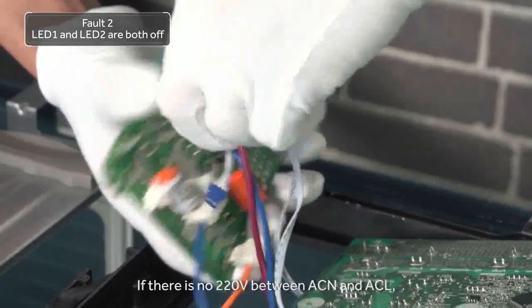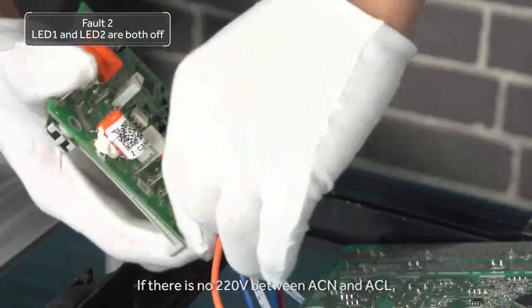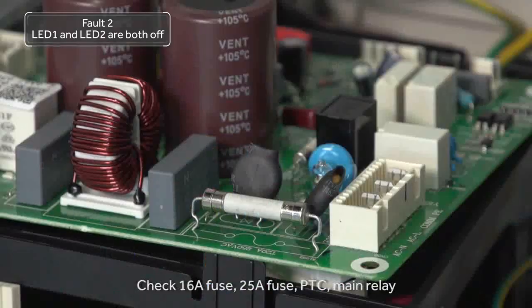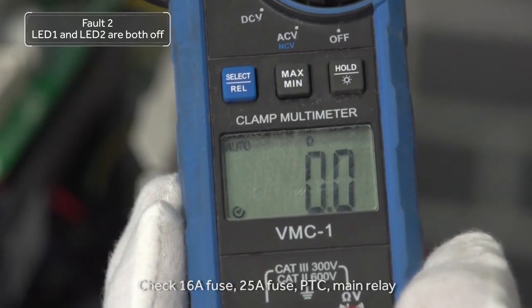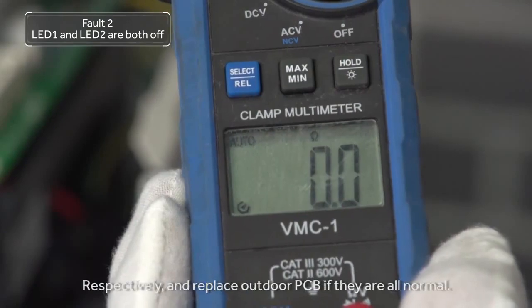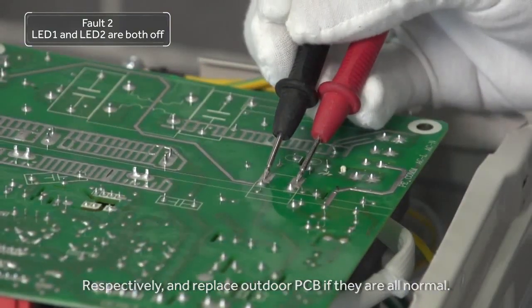If there is no 220 volt between AC-N and AC-L, check the 16 ampere fuse, 25 ampere fuse, PTC, and main relay respectively, and replace the outdoor PCB if they are all normal.